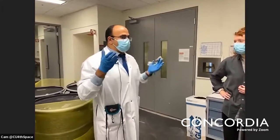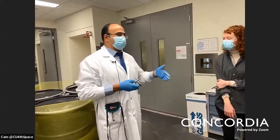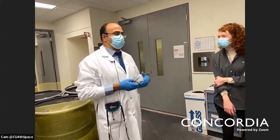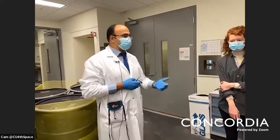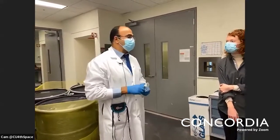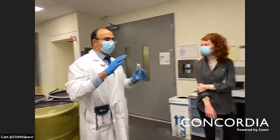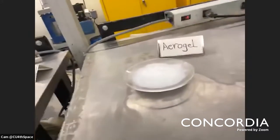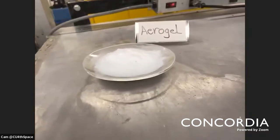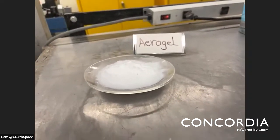So the weight of the concrete is one of the main limitations, affecting how many laborers are needed for the construction process itself. So achieving very light concrete will be one benefit. The other thing, from the thermal point, when you add aerogel, you are going to make your concrete more of an insulation material, which is going to prevent loss of moisture, loss of thermal and heat. So this will be the benefit also. So we have two things.